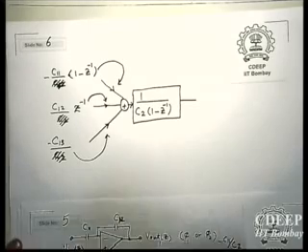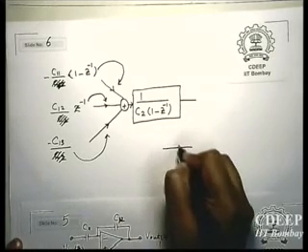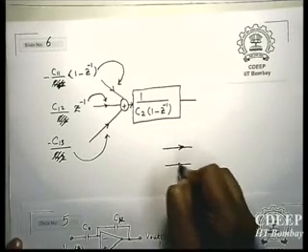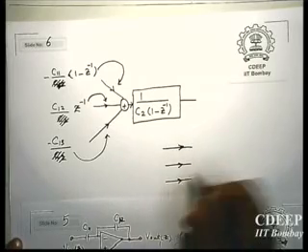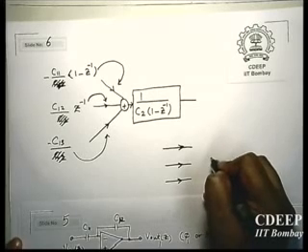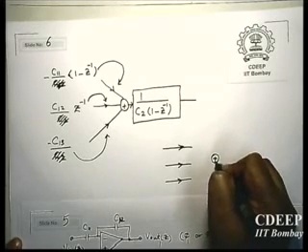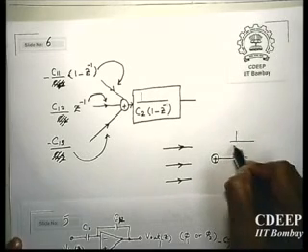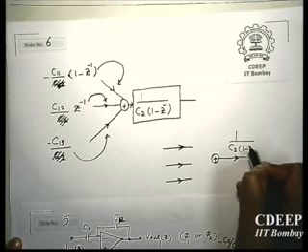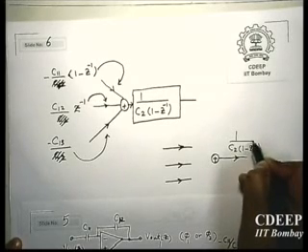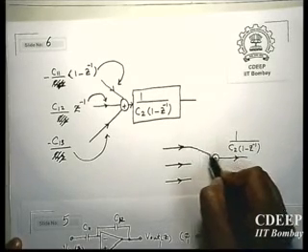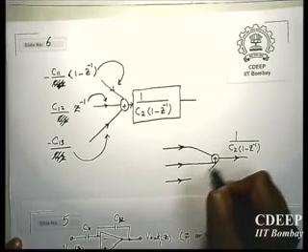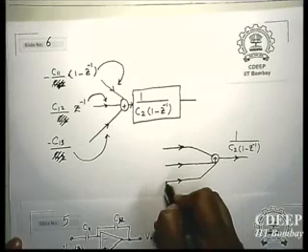So eventually, to simplify, you will always have in your signal flow graph one of these three on the branches. Then you will have summing points which will have the output branch in the form of 1 upon C2 into 1 minus Z inverse. For example, if you have 3 of them, in general they will be like this.